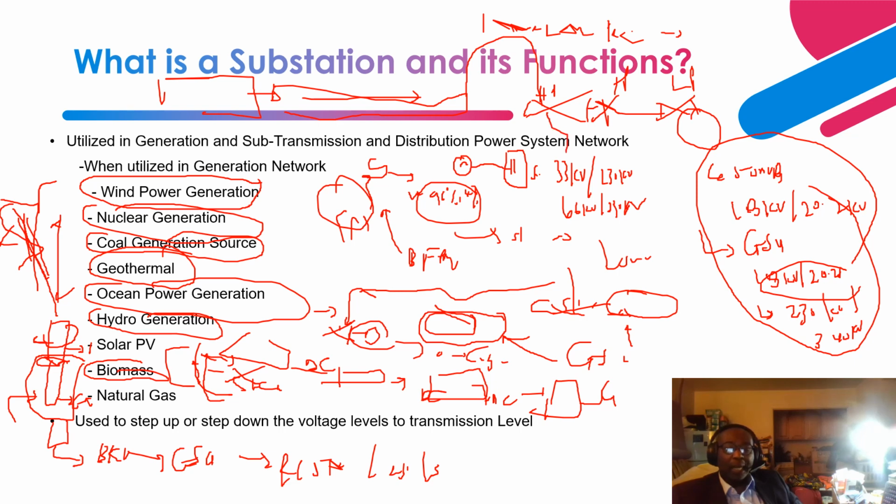Then, as the steam flows past the steam turbine blades in the high pressure section, it comes back and goes through the reheat section of the boiler. The goal of the reheat section is to heat it more to make the steam as dry as possible.